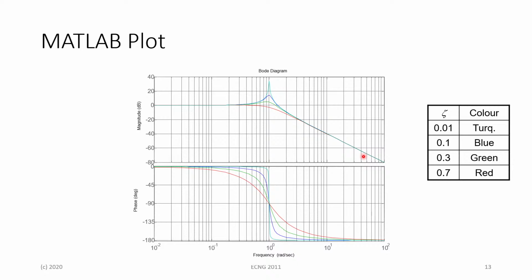And once you cross 0.707, or 1 divided by root 2, there's no longer any resonance within the system throughout the entire magnitude and phase graphs. So you'll just get your nice straight, smooth Bode plots for magnitude and phase.